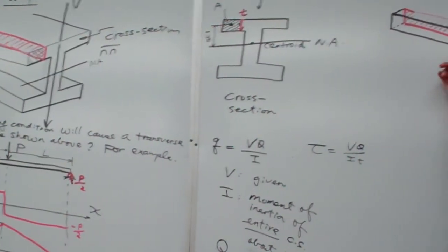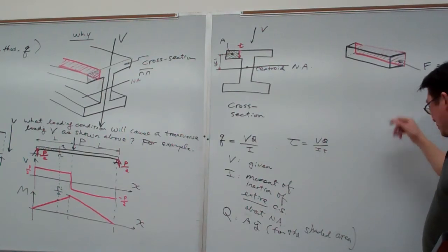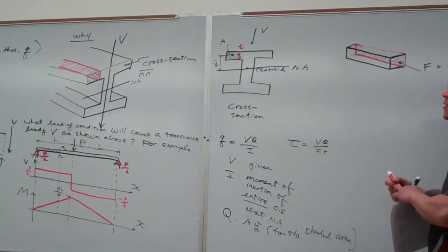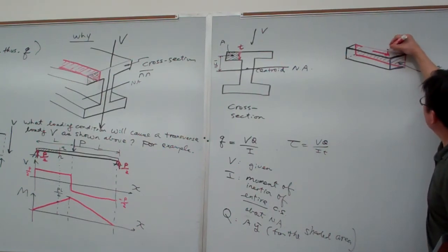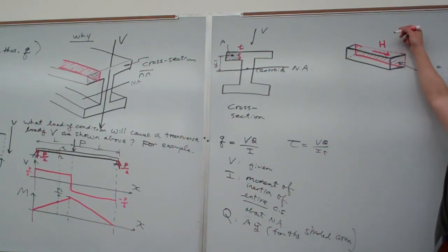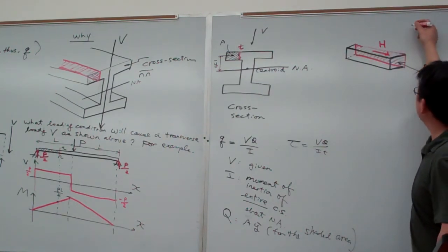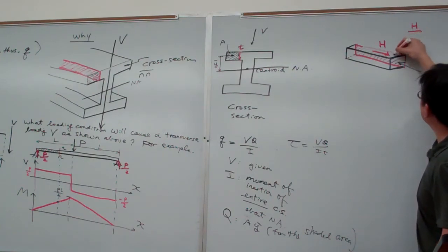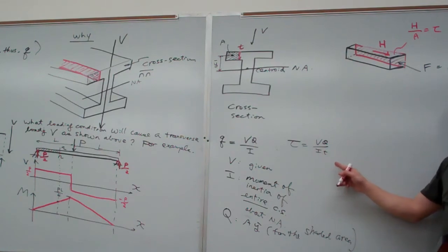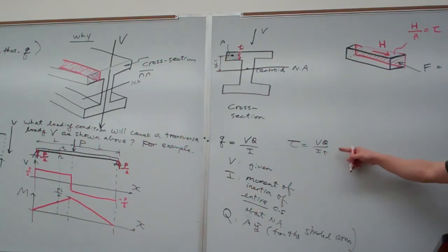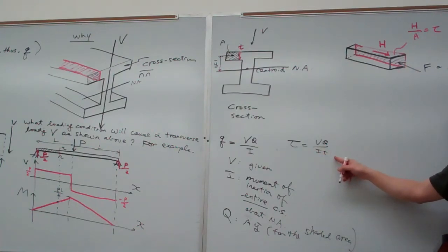So this free body diagram must be in balance. That means on the red internal cut we expect a force in some direction, we call it H, to balance. What we obtain is H divided by this area A, which is our tau. We are already able to calculate the magnitudes, so we don't have to worry about this kind of drawing. Everything is reflected in this formula.